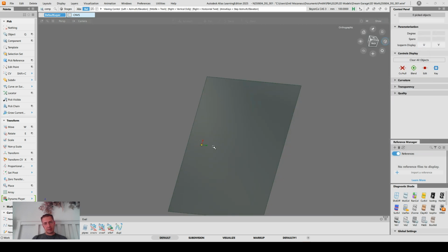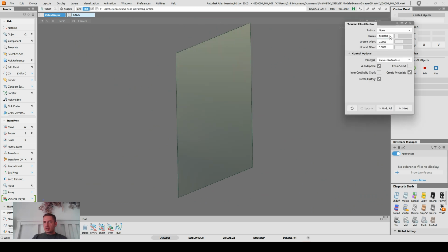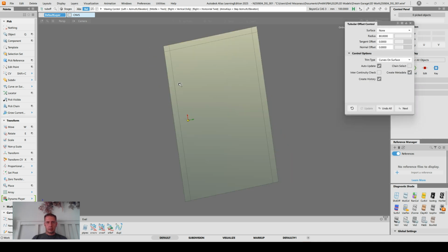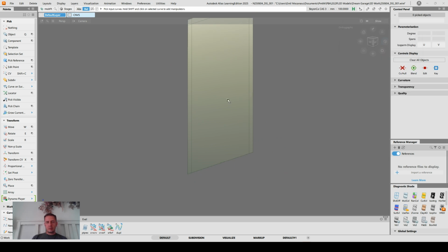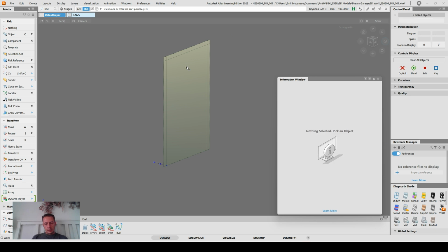That surface, that's enough. Because the rest will be done by the history. And I'll take 2 door offset, put a radius of 80 millimeters, and have it get some curves and surface on there, the next one there. And now I'll just take a line. I was thinking to use a draft tool, but I'm not a fan of the draft tool because as soon as I change something on it, it messes everything up. So 100, let's put 300. I just want to overbuild there. Right.